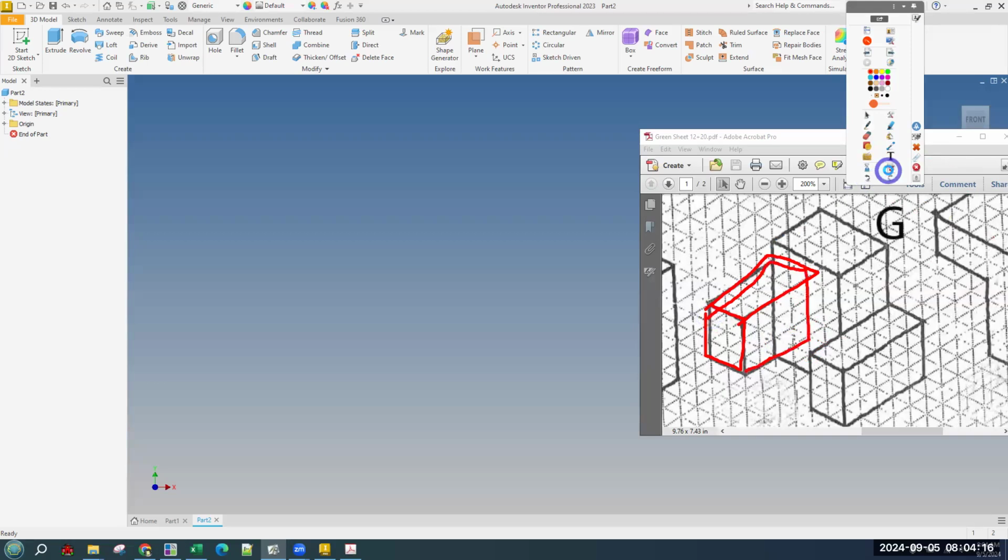I don't know if anybody has those anymore, but we have the sort of this one arm over here is one part. This tall center part is another. And then the third part is the other arm, or whatever you want to call it. Okay, so I'm going to draw this one first. And on the front plane, I'm going to make a rectangle that's 3 tall and 2 wide, and then extrude it all the way back, which I think we can infer is a mirror of this one. So it's extrusion of 5 deep, even though we can only see 1, 2, 3. We can only see 4, but I don't think it ends short. So like I said, rectangle, 3 tall, 2 wide, extruded 5 to start.